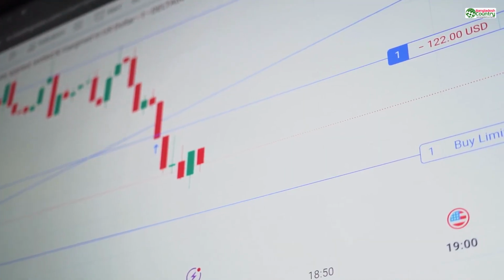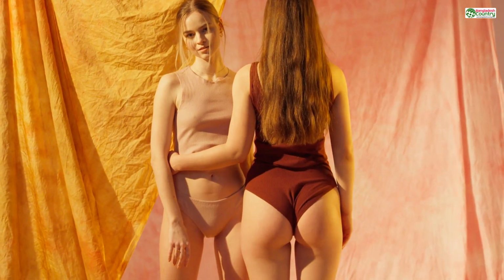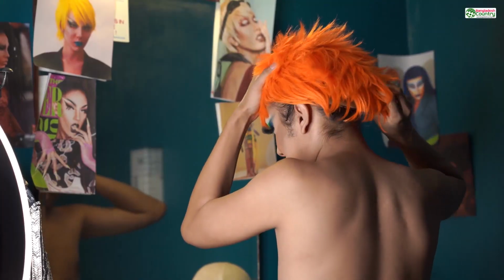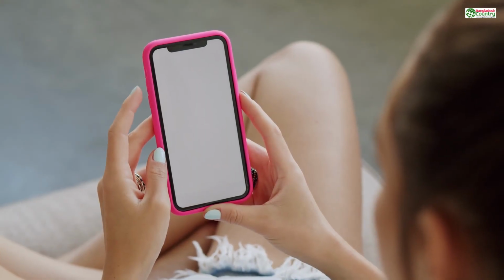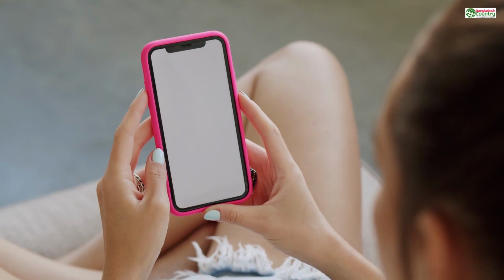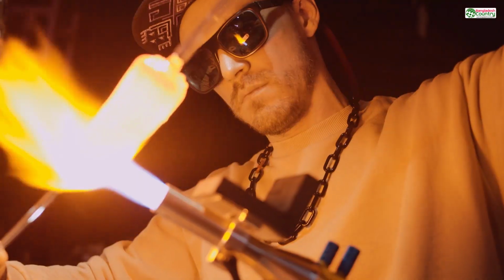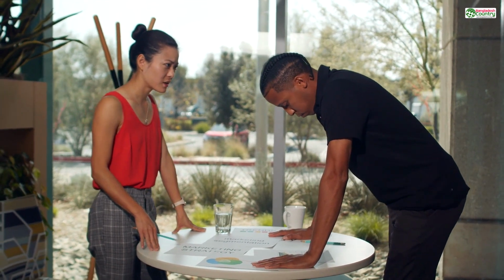So, you've run the analysis. You've patched the holes. Your model is now a mathematically perfect, sealed, watertight object. You're ready to upload it and print, right? You're finally safe? Not even close. Because you could have a perfectly sealed model that is as thin as a single sheet of paper. And the moment the printing service's machine tries to build that paper-thin wall with molten plastic or laser-fused powder, it will instantly disintegrate, crack, or warp into nothing. You've solved the leakiness, but you haven't solved for the laws of physics.